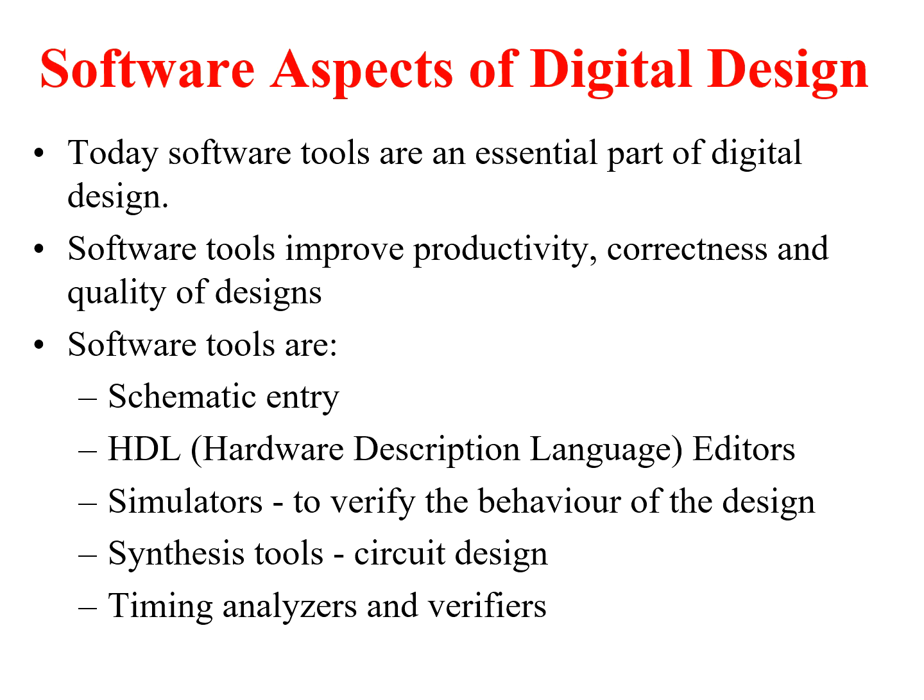The software aspects of digital design. Today the software tools are an essential part of digital design. The software tools improve the productivity, correctness and quality of design. We have some tools for that. The first one is schematic entry with the hardware description language, in which the circuit will be designed. The next is a simulator. The simulator is used to verify the behavior of the design. The next tool is a synthesis tool. Here we are designing a circuit, and the last one is the timing analyzer and verification.